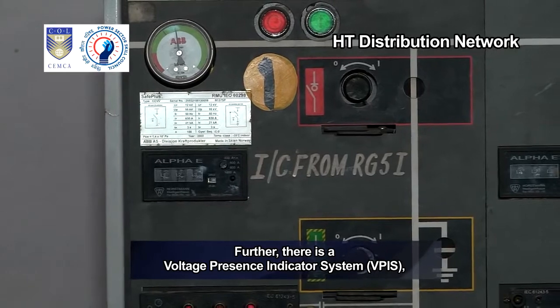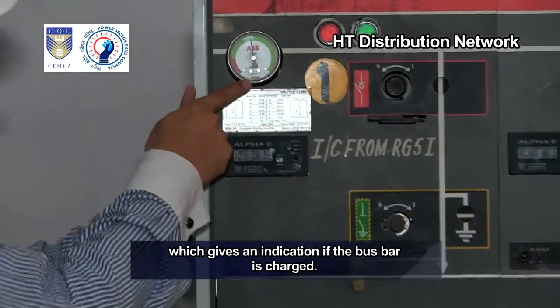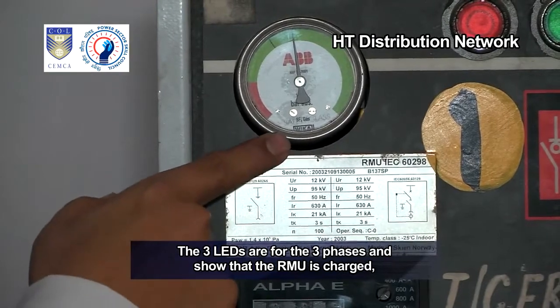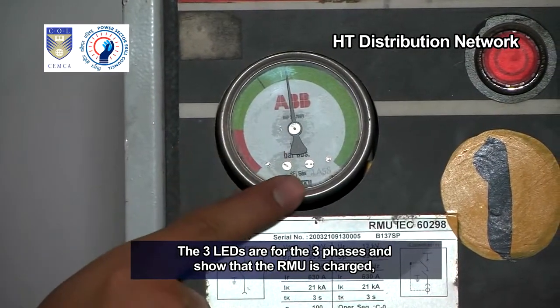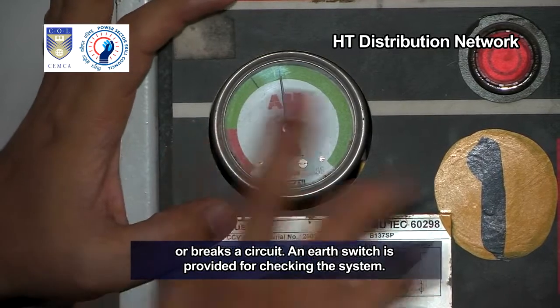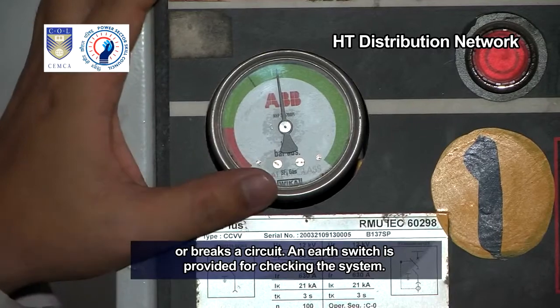Further, there is a voltage presence indicator system, VPIS, which gives an indication if the bus bar is charged. The 3 LEDs are for the 3 phases and show that the RMU is charged and all phases are energized. The isolator has a switch which makes or breaks a circuit. An earth switch is provided for checking the system.